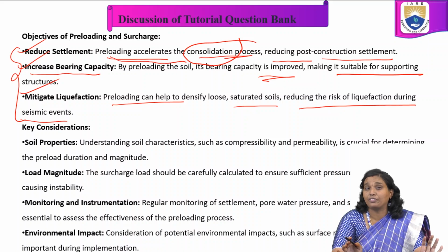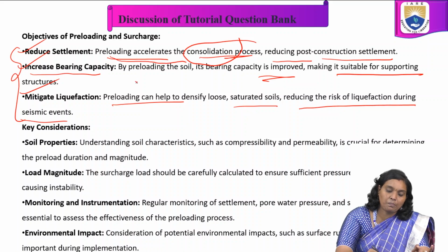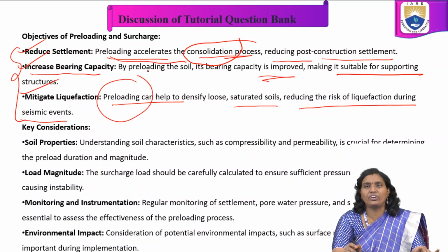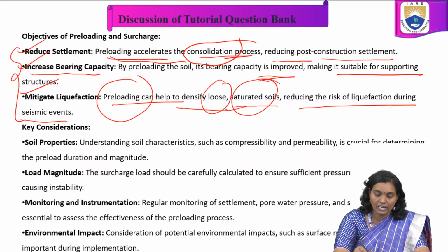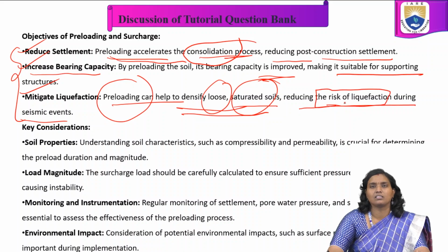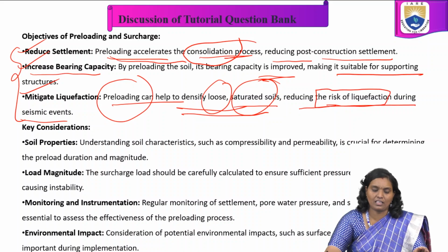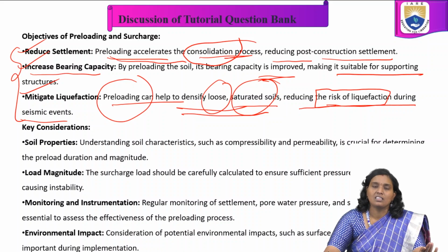Whenever seismic effects happen in that particular region, the risk of liquefaction is reduced because preloading densifies loose and saturated soils. These are the main objectives of preloading and surcharge.